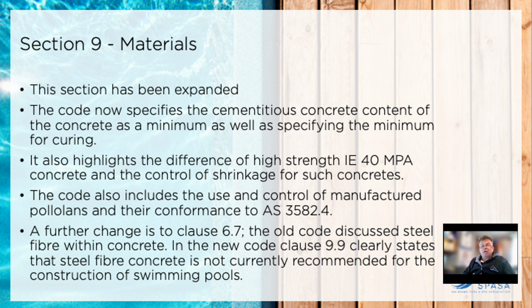You can design it exactly like a steel bar and it can be used exactly like a steel bar with one, to the best of my knowledge, one difference, and that is that you have to have these bars put into shape so that when they get delivered, you can just place them in, because you can't really bend them easily over a certain radius. But it is a good option to be able to use. So, key point of this: steel fibers are out.